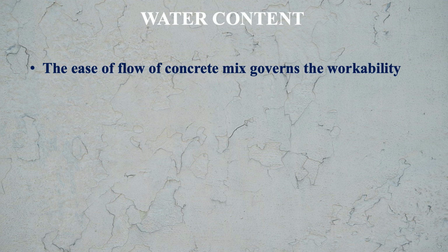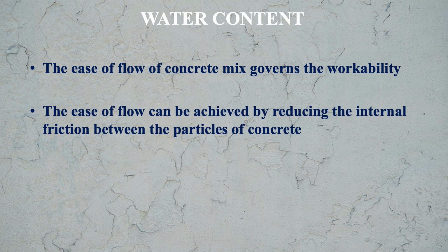The ease of flow of concrete mix governs the workability, as you know. And the ease of flow can be achieved by reducing the internal friction between the particles of concrete. Means the internal friction which is there between the ingredients of the concrete. So if we can reduce this internal friction, then we can increase the workability.